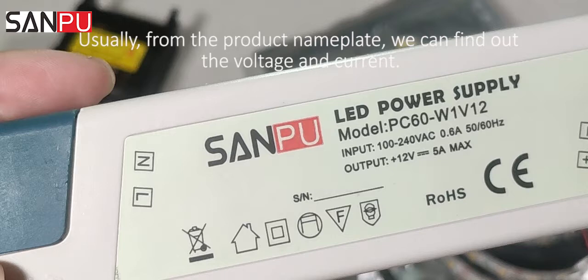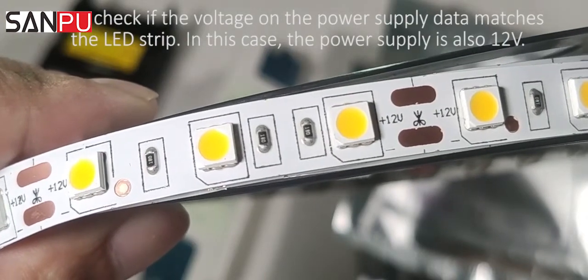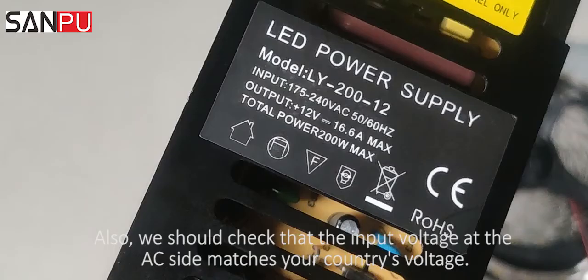Usually, from the product nameplate, we can find out the voltage and current. Now, check if the voltage on the power supply data matches the LED strip. In this case, the power supply is also 12 volts. Also, we should check that the input voltage at the AC side matches your country's voltage.